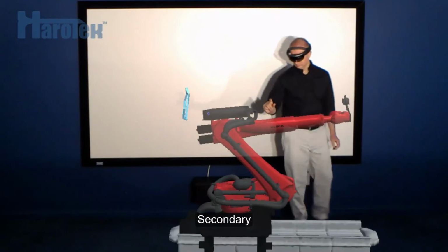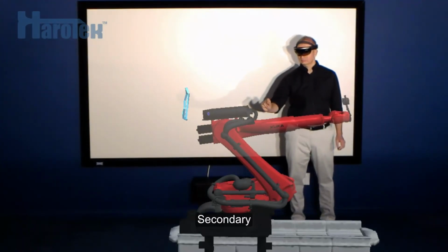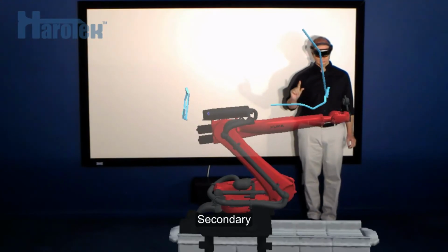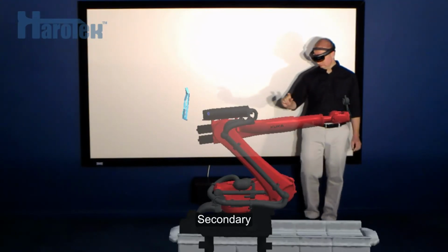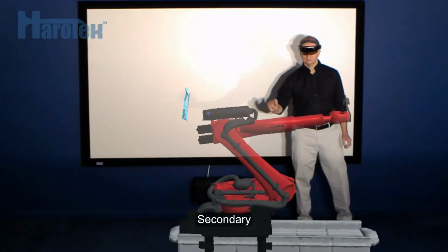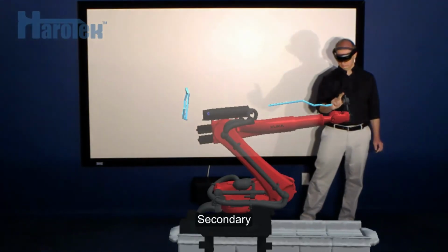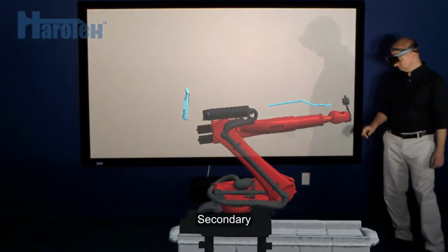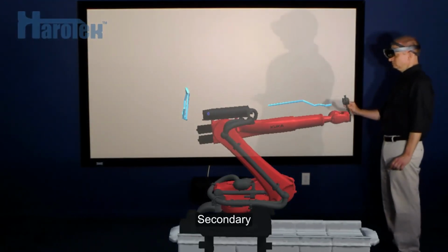Also, when the hand gets near the edges of the zone of hand detection of the HoloLens, the hand position gets very inaccurate. This is why it is better to make small hand movements, try to keep the headset leveled when using the 3D markers, and release the air tap while the hand is well within the detection zone of the HoloLens.